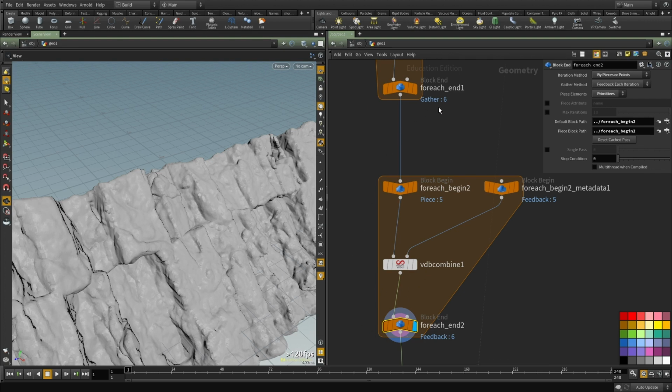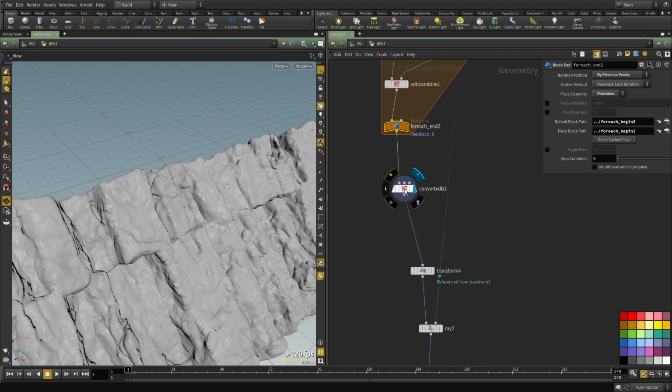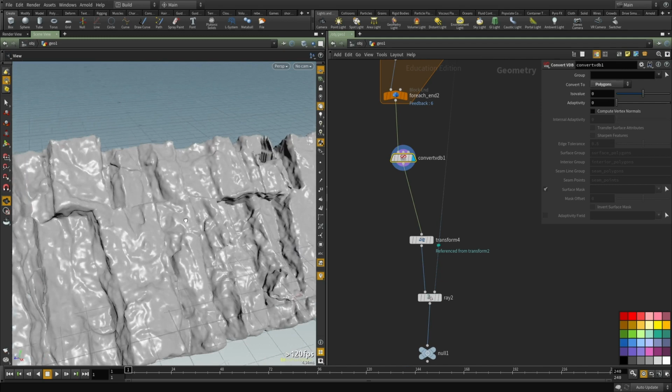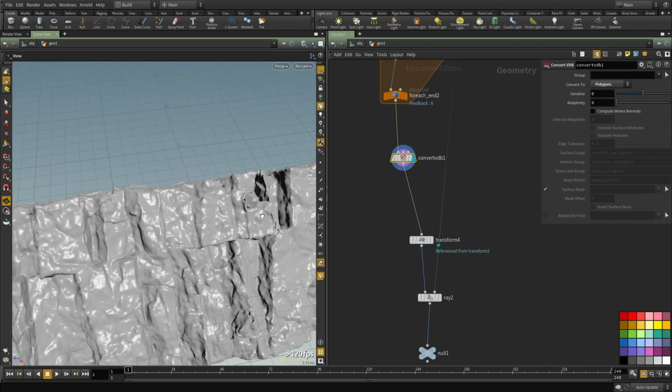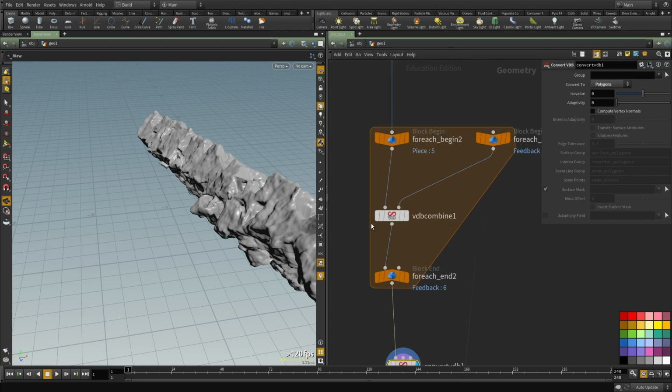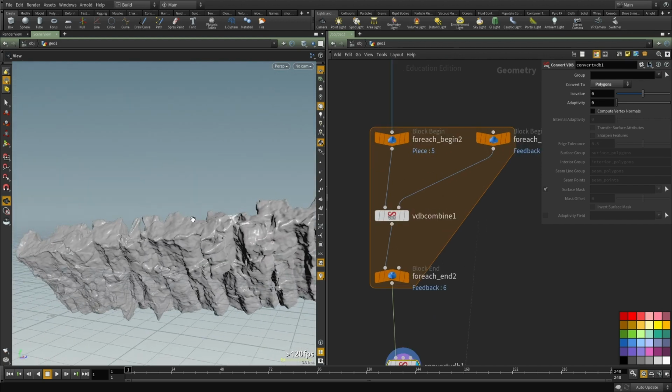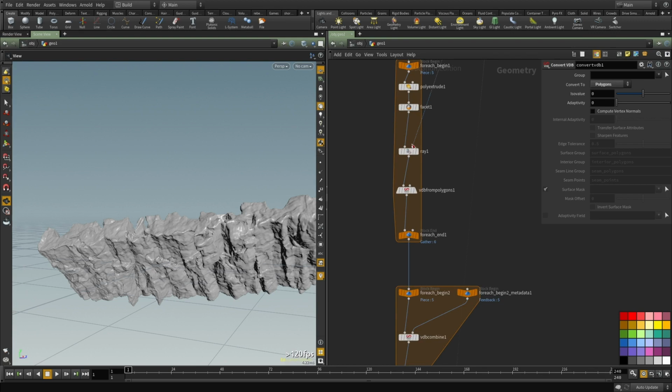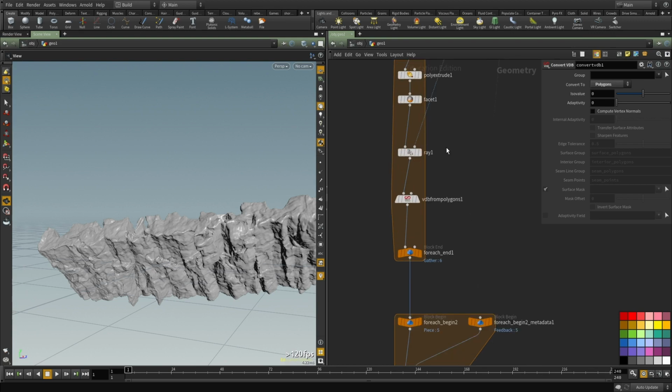The result is going to go into this node, it's going to stream in another volume, and then combine that together. And all of that is then converted into a mesh. And without VDB, without the signed distance field, we won't be able to do this, and without the ray SOP and that clever feature. And I think hopefully this makes sense to you guys.